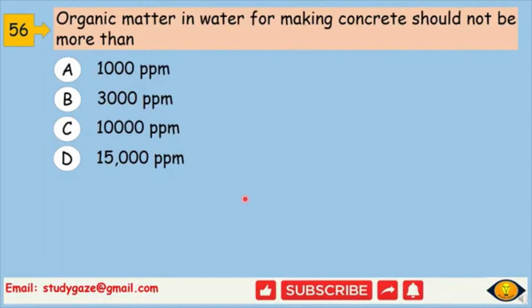56. Organic matter in water for making concrete should not be more than 1000 ppm, 3000 ppm, 10,000 ppm, 15,000 ppm. Answer will be B. 3000 ppm.